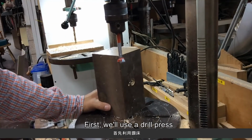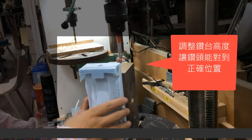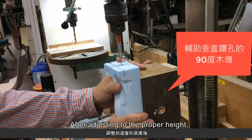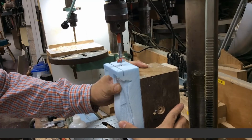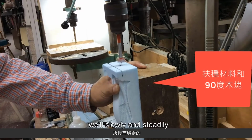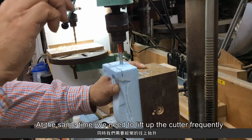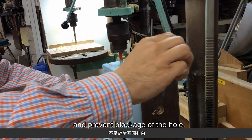First, we'll use a drill press to cut out the round hole needed for our high-pressure cylinder. We'll use a 90-degree wood block to keep the car body perpendicular to the drill press after adjusting to the proper height, and hold our material and wood block. We'll slowly and steadily cut out the hole needed for the high-pressure cylinder. At the same time, we need to lift up the cutter frequently to remove the scraps for a smoother machining and prevent blockage of the hole.